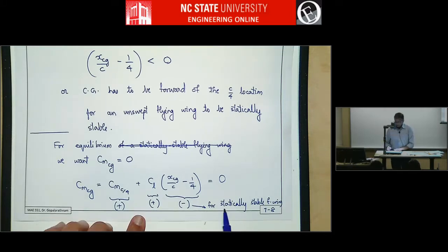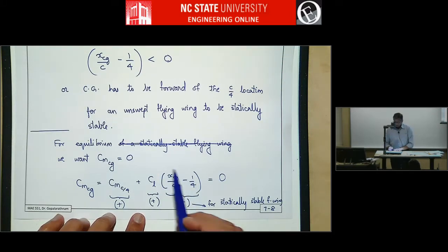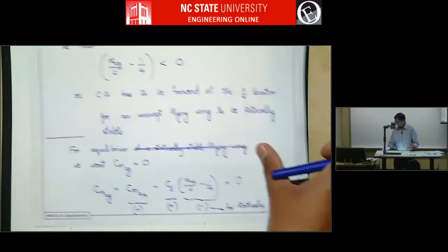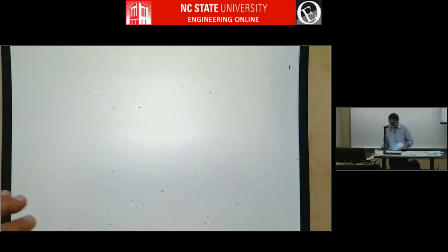Anyway, we are talking about statically stable flight. So it turns out that the pitching moment about the quarter chord for the airfoil has to be positive, otherwise you can't have equilibrium.